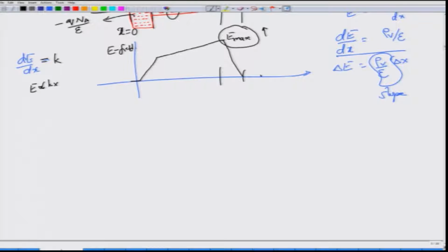Now this is for the electric field, but what you are probably interested in, if you are designing a photodiode circuit, is the current and voltage characteristic, right. If you go back to a simple PN junction diode, you already know what the current and voltage characteristic will be. You start typically with some very small dark current, a very small negative current, and then the current will be 0, and then it will start slowly to rise, and then eventually it will rise sharply, right. There is this cut-in voltage on the positive voltage axis. So if you are forward biasing, you are going to get this. This is for the case when there is no illumination, therefore this current can be thought of as the dark current.